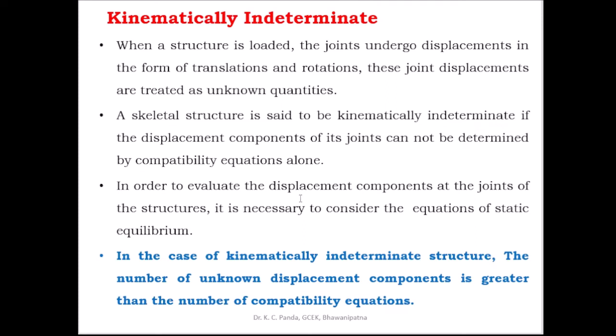In order to evaluate the displacement components at the joints of the structure, it is necessary to consider the equations of static equilibrium. In the case of a kinematically indeterminate structure, the number of unknown displacement components is greater than the number of compatibility equations.